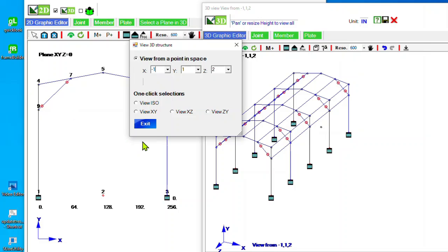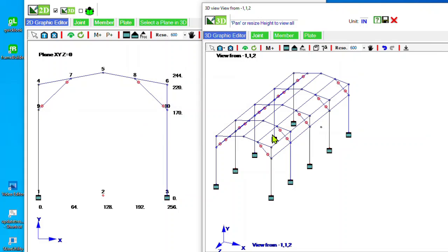The box button is very powerful, because you may slice the model into smaller boxes, and construct them accordingly. Work the box button with the point of view button, it is easy to construct a complex model. Back to define the properties of interframe members. They are all made of W10 by 22, A36 steel.